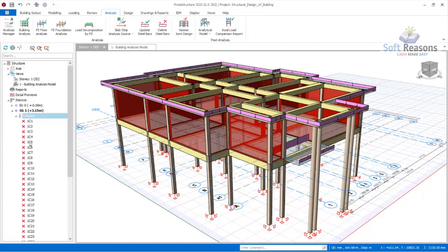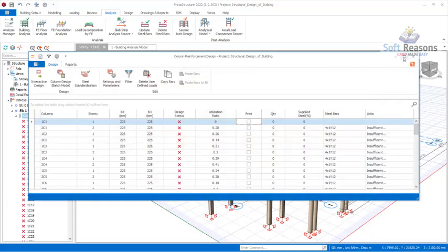Alright, so then click on this and then come over to it. You can design all of this reinforced concrete column if you choose the first option, these options right here, RC columns/wall design. Okay, and then RC column/wall design active story. But this is just a story building, so let's do all of the reinforced concrete column design successfully.